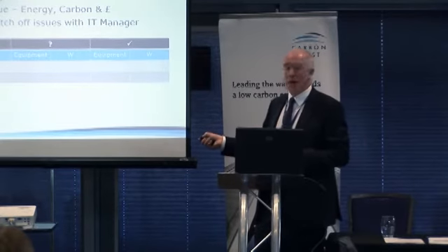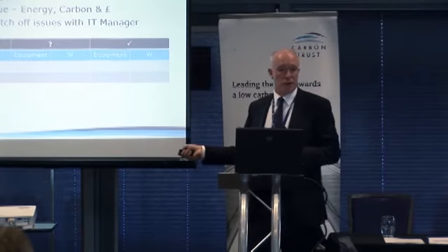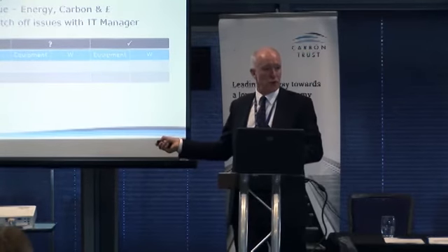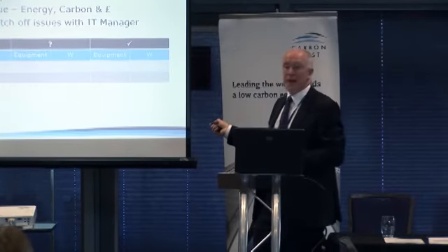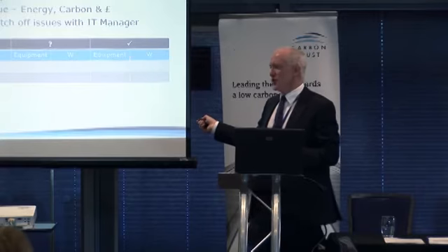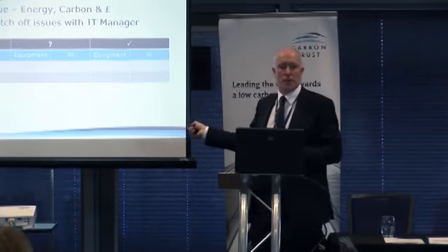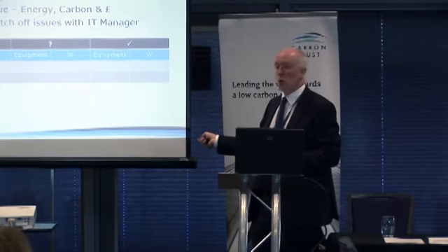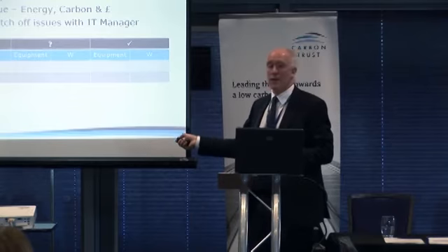And I walk around and I record all of the equipment that I can switch off. And I would switch it off as I go around. Everything on standby, switch it off, record it, and estimate the wattage that it may be. I mark up anything that I can't switch off: fridges, freezers, security systems, whatever it is. These things cannot be switched off, so I record what can't be switched off and what the wattages are.